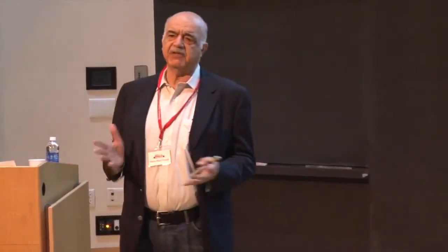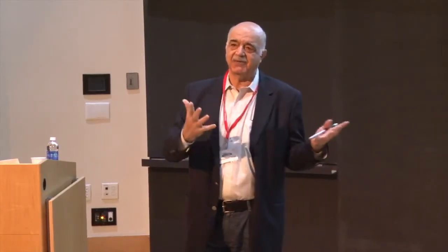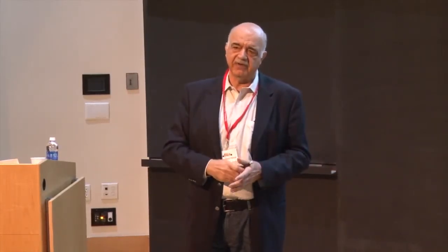Yes, Vera. What is the frequency band with each device? So each CMOT array operates at one frequency or any frequency? So typically they're about 100% fractional bandwidth. So the 1 megahertz device, we can run it anywhere from 0.5 to 1.5 megahertz if you want CW. So the idea would be to then come out of here into a switch box and maybe an inductor box to sort of tune it for the frequency of operations, and then to the power supplies, right? So at least for high-flow application, that's how I see them. But we can certainly tune them over a very broad range.